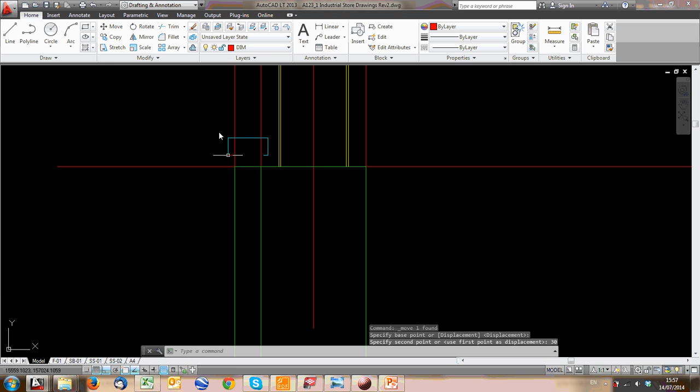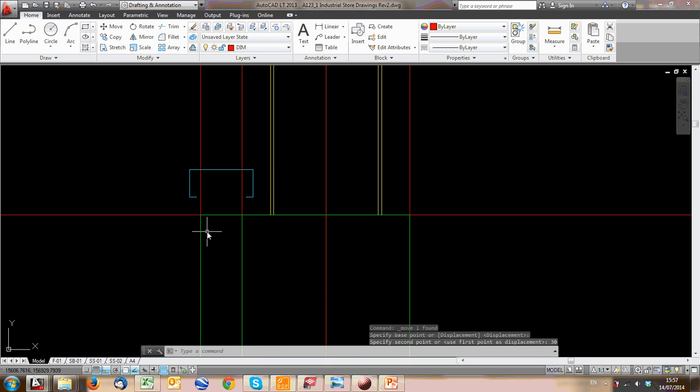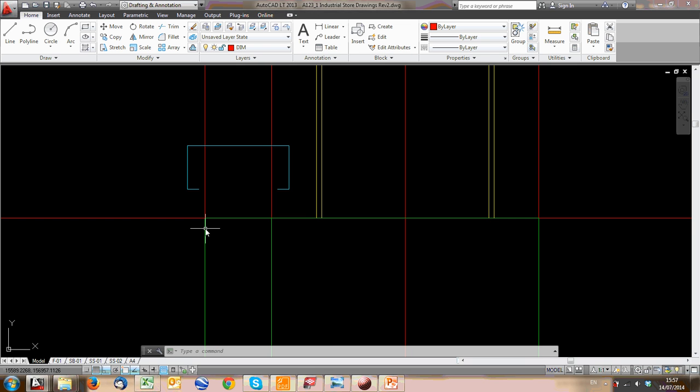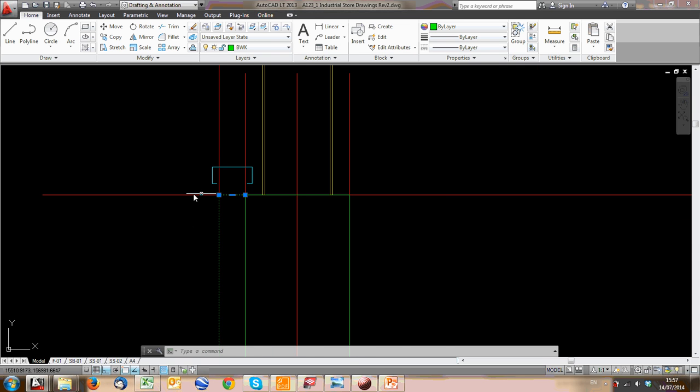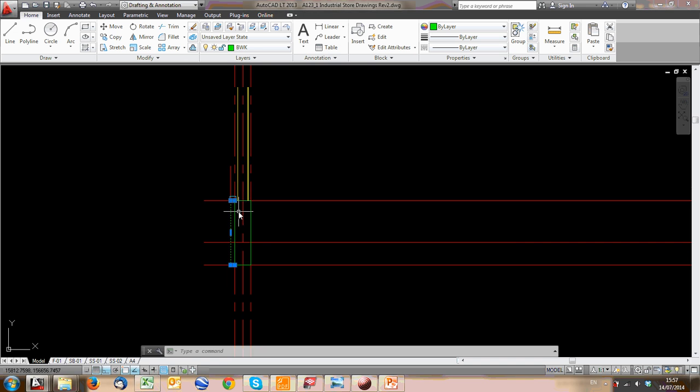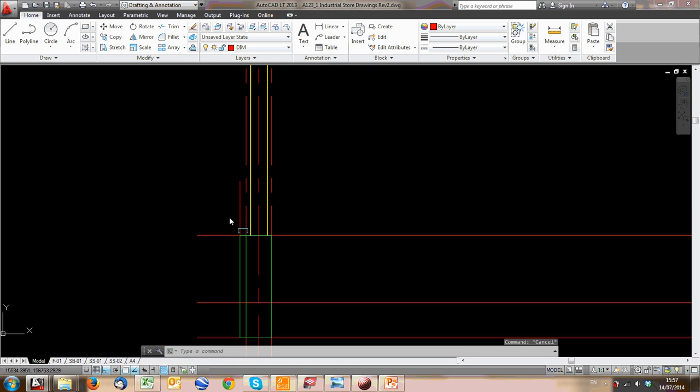And there we go. That's where the girt should be now, because either the brickwork line or the sheeting line is going to determine it. As you can see, the brickwork line was further out than my girt. Therefore, it governs it. So I could set out my brickwork 30 mils back, and there we go. There we start our line.